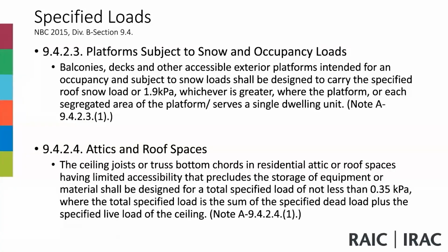So these are the platforms, decks and balconies, exterior platforms where people are going to sit or they're going to be used. You need to make sure that they're going to be designed to carry a specified roof snow load or 1.9 kPa, whichever is greater, where each segregated area of the platform serves a single dwelling unit.